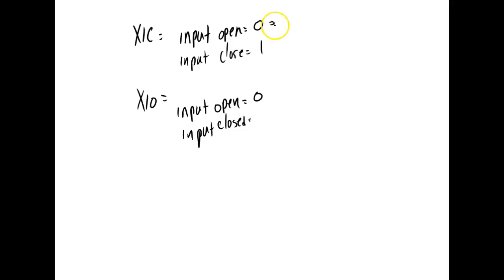Now up here, this is false, this is true. That's what the PLC examines that as, right? Down here, this is going to swap. If this is true, this is going to be false. So down here, if it gets a 0, the PLC interprets it as a what? True.